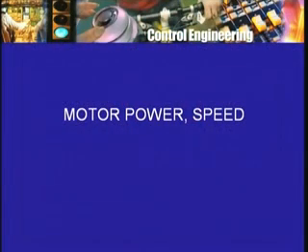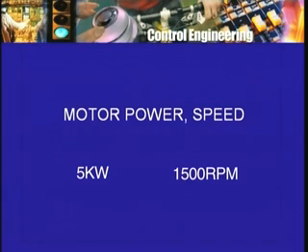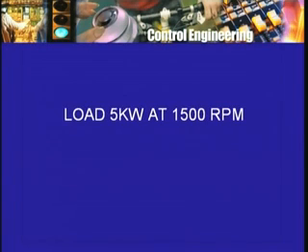So naturally now the motor that I have to choose has to be such that it can deliver power of, in fact, more than 5 kilowatt at a speed of 1500 rpm, and perhaps even a higher speed if it may be required. So accordingly then one will choose a motor. So one will say we want a DC motor of about say 6 kilowatt and 1500 rpm.